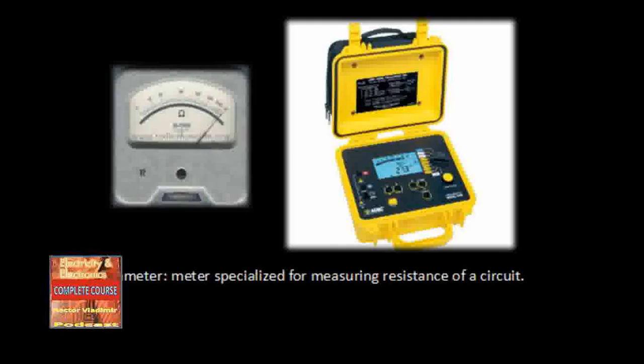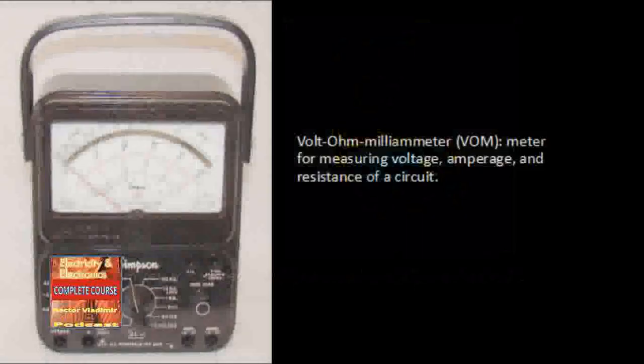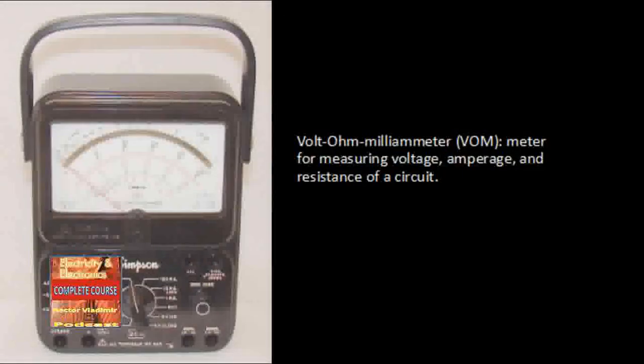To use the ohm meter, first short the test leads together. This applies 0 ohms across the meter. Adjust the ohms adjustment knob until the needle points at 0. The needle should deflect from its position at rest on the left to the zero resistance indication on the right side of the scale. If the needle does not deflect, it is possible that the battery is dead or extremely weak. After the ohm meter has been calibrated to read 0 ohms when the leads are shorted, you can make a reading of an unknown resistance by placing the unknown resistance between the test leads.